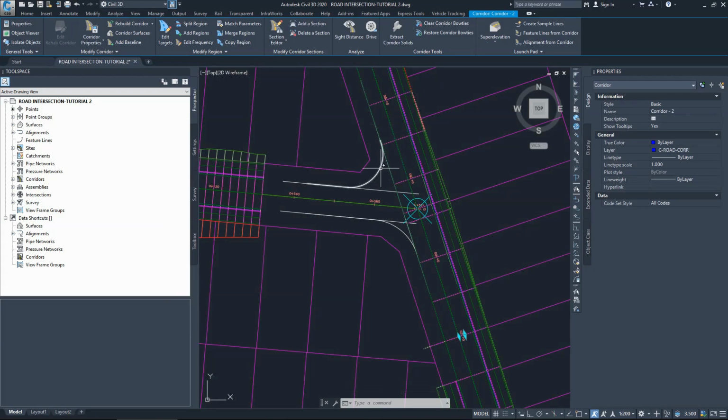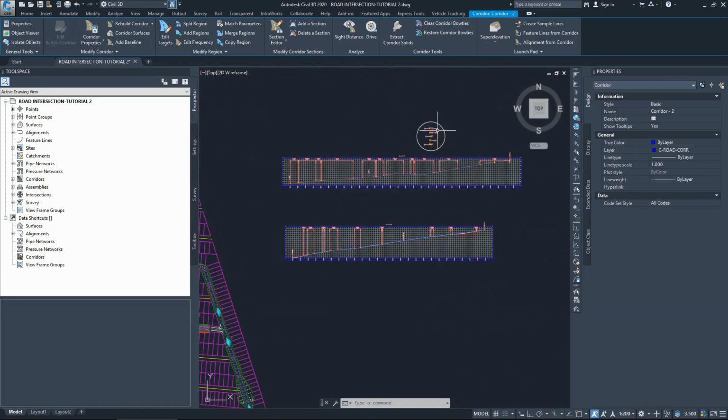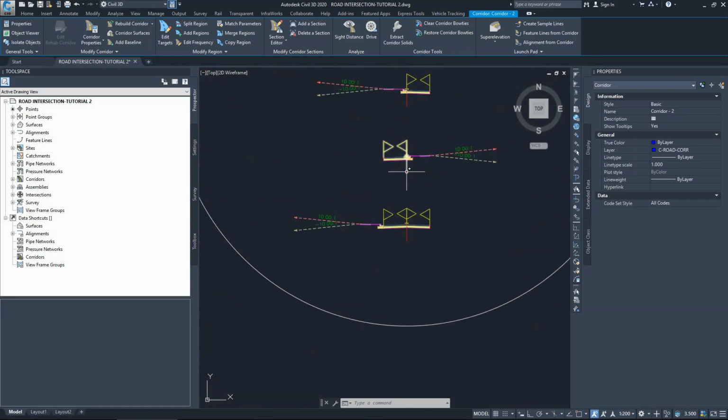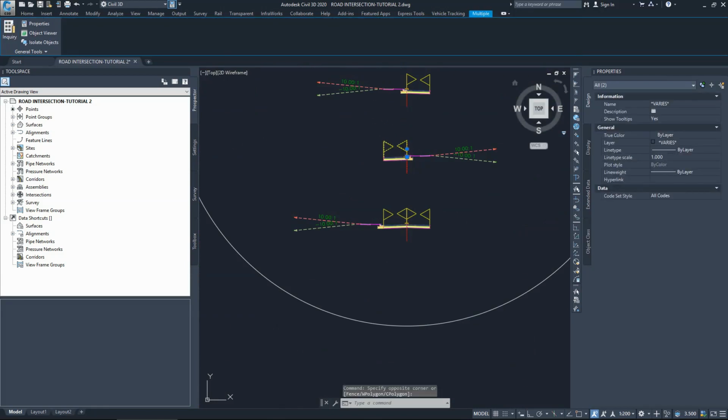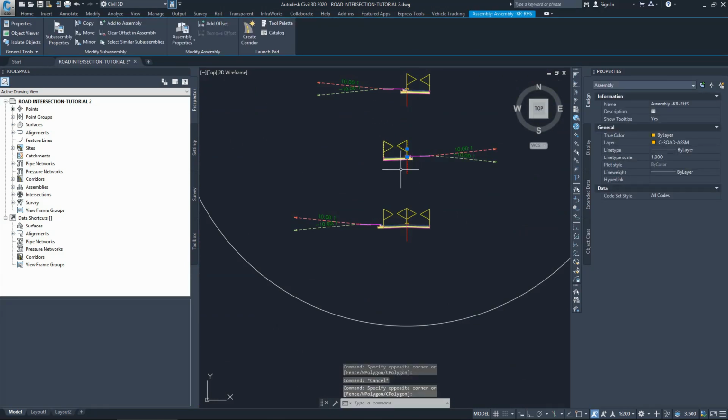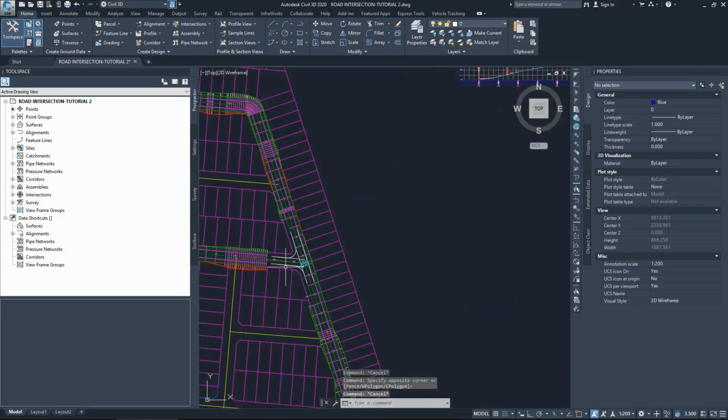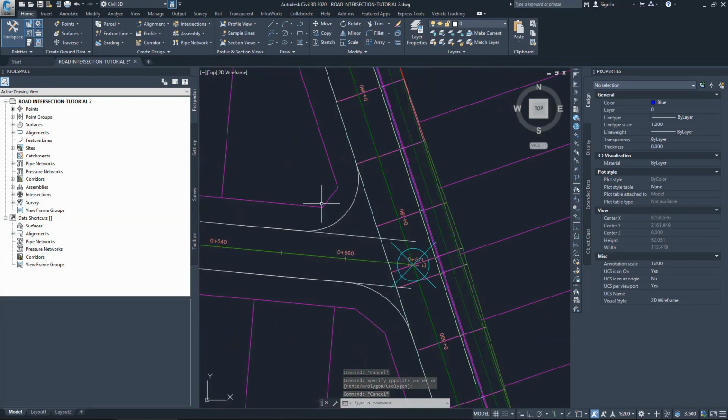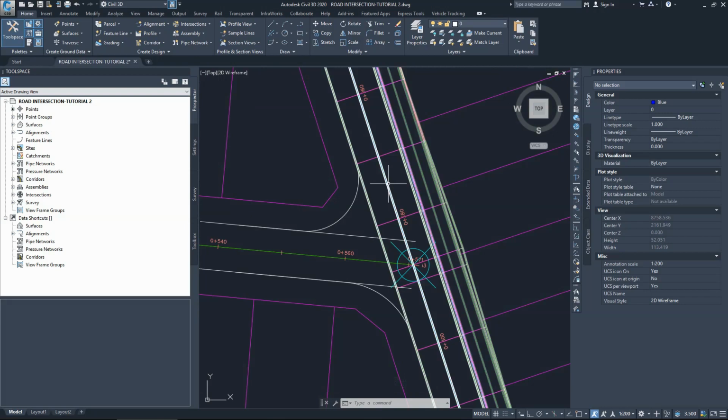That means I need a cross section with the lane on the left hand side, curb, gutter, sidewalk and daylight on the right hand side. So that would be the lane on the left hand side and all of those. So we call this one here a right hand side curve return. So I'll choose that. I'll go back to here, select the corridor.